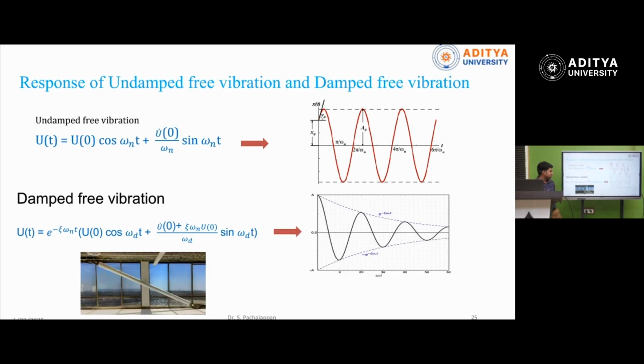So that is the reason in multi-story buildings they use dampers. In this cylinder, they fill a high viscous fluid, which is connected to the floor and then the roof level. So during an earthquake, what will happen? This floor will be pushed in this direction, the roof will be pushed in this direction. So it is going to control the displacement.